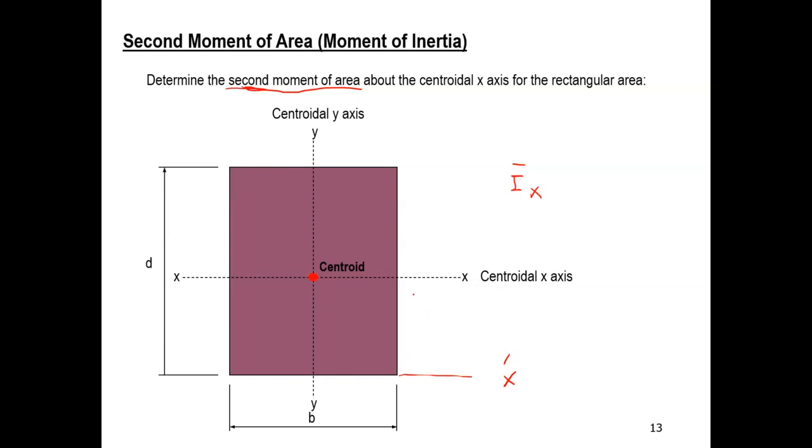And that brings us to the interesting concept called the parallel axis theorem. With the parallel axis theorem, if I provide you with the second moment of inertia about one axis, you can add a penalty term to find the second moment of inertia about another axis, which is parallel to that and has a distance of d.